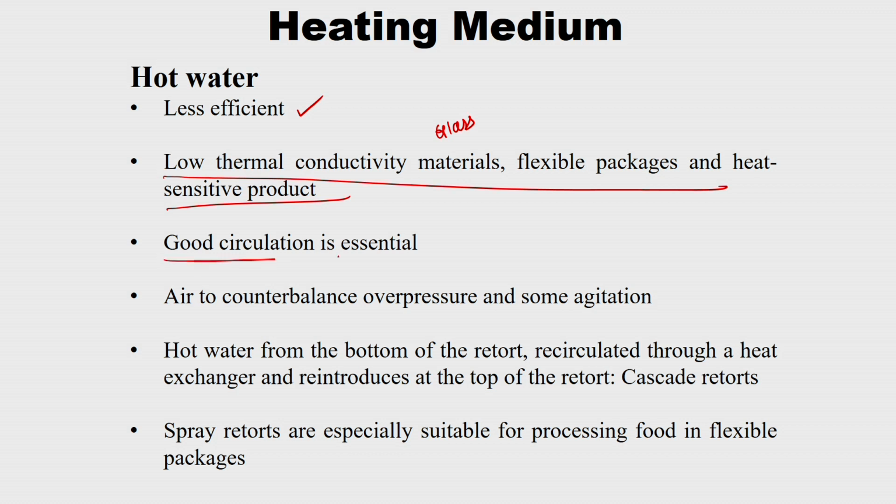So, if good circulation of hot water is not there, then we will develop cold points in the heat transfer medium as well. So, to avoid that, good circulation is also essential, and air to counterbalance overpressure and some agitation. Sometimes along with the hot water they send air also to counterbalance the overpressure, and sometimes agitation is also needed to enhance the heat transfer, right.